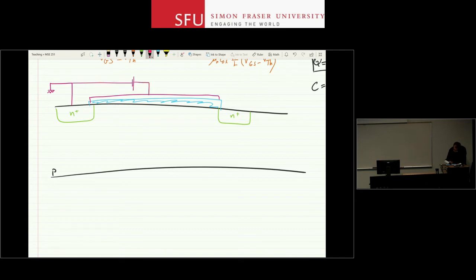So I'm going to choose the source to be ground, make my life a bit easier, and then apply 2 voltage sources between the drain and source and gate and source. And I'm monitoring these 2 currents. So there's the ID and there's IG. What is IG? I'd like you to maybe pause the video for a second and tell me what you think IG at DC is.